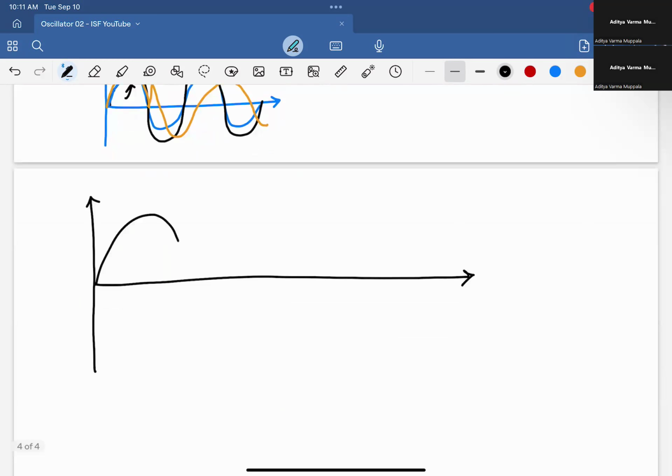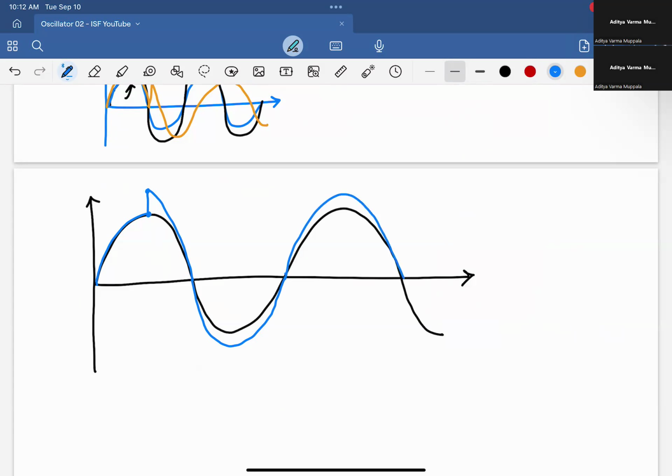Okay, so let's say I have my sinusoid like that. And the authors, at least in the paper, argue that if I introduce an impulse here, so only amplitude changes because the phase of this point and this point are the same, then the impact on the phase is zero or negligible. Right? Whereas if I introduce an impulse at this location, then when it comes down, a lot of phase has changed. Right? So the impact on the phase is much larger.